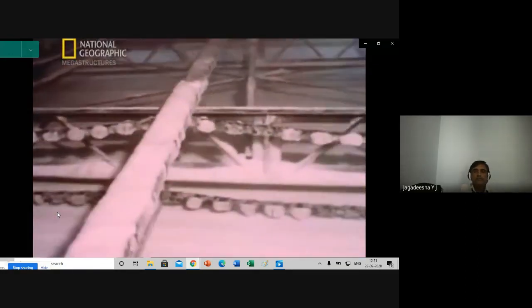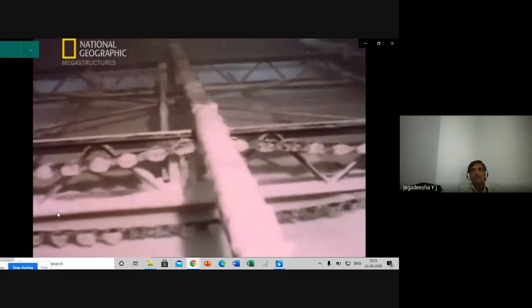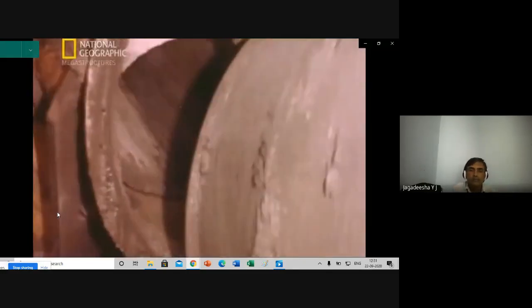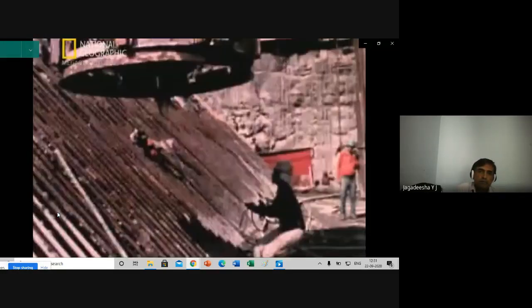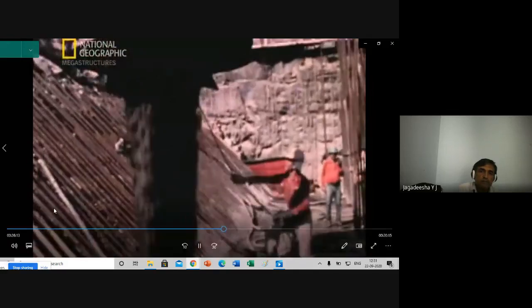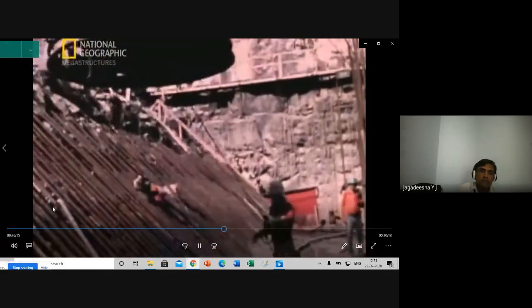The stone was washed with icy water and blasted with cold air. Using a large number of ice chips, we were able to produce concrete with a mean temperature of just 4 degrees. And because we had an efficient transportation system, the concrete only reached 7 degrees by the time we were pouring it into the molds.